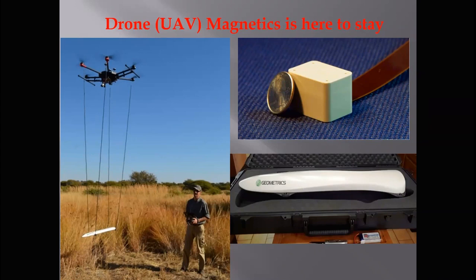Because like most magnetometers, they're actually sensitive to the direction that the field is passing through them. And in addition, we have 2 of them in here. We can have one at one orientation and one at another orientation, and therefore when we flip the drone around, we can pick up the magnetic field more accurately with one or the other. We can take an average, or we can say, right, we've got a better result from this drone in that orientation. Or you can just have them both in the same orientation.